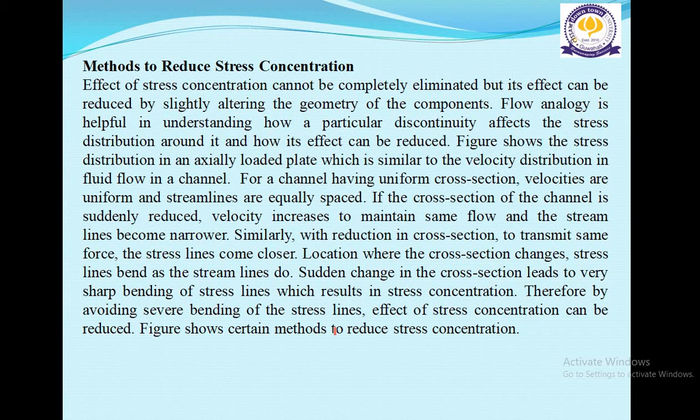If the cross section of the channel is suddenly reduced, velocity increases to maintain same flow and the streamlines become narrower. Similarly, with reduction in cross section, to transmit the same force, the stress lines come closer. At the location where the cross section changes, stress lines bend as the streamlines do.